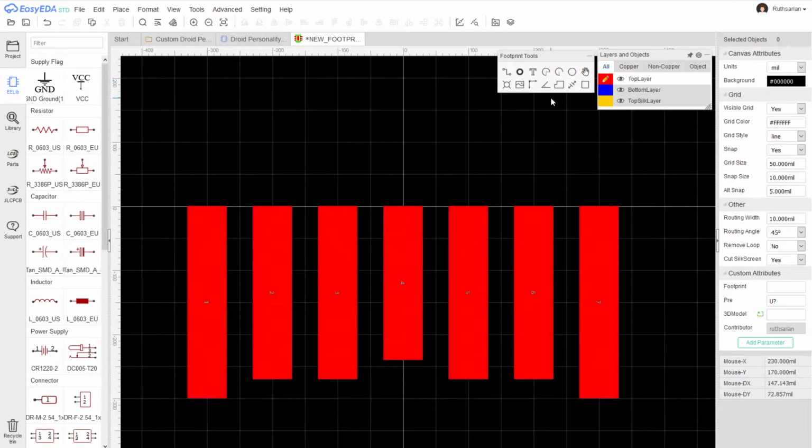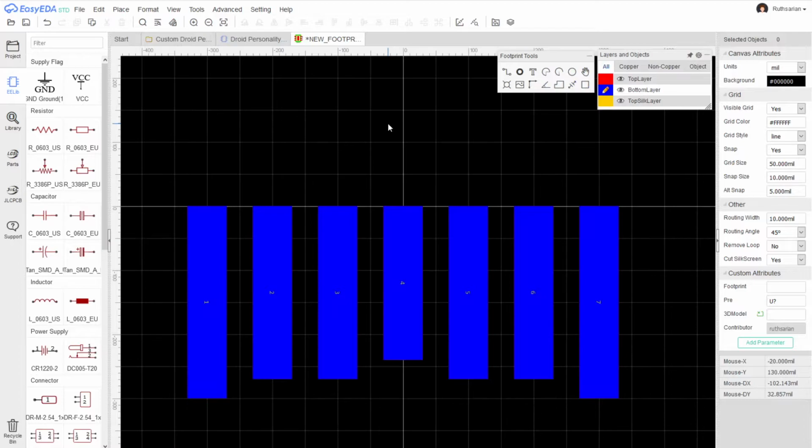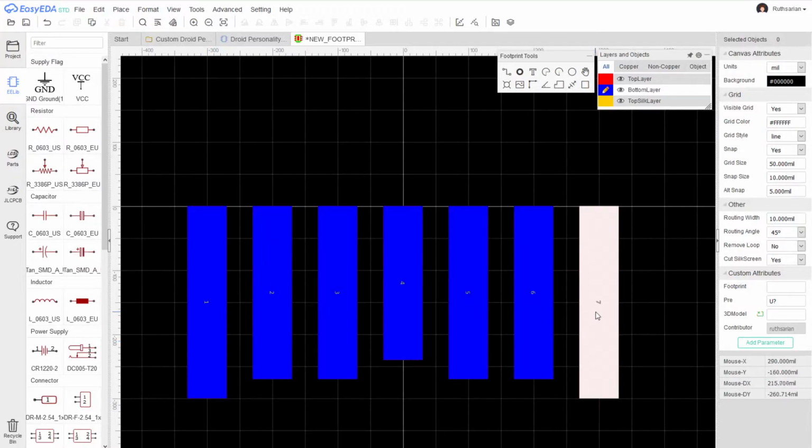So when we're looking at it from the top of the PCB, pin 1 of these fingers is on the left. When I highlight the bottom layer, I'm looking at the bottom layer as if I'm looking at it from the side of the top layer. So I'm seeing the mirror of what this will look like when it's flipped over. In other words, the numbering here needs to be changed.